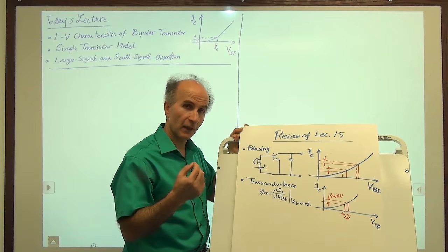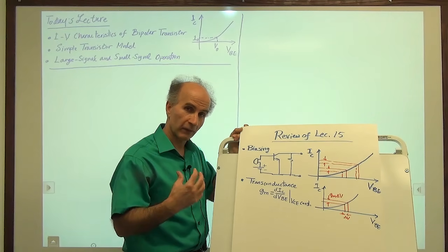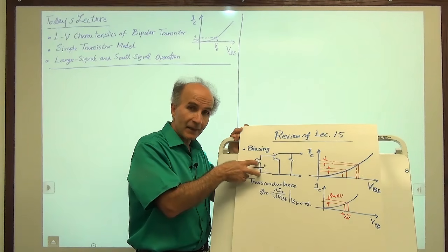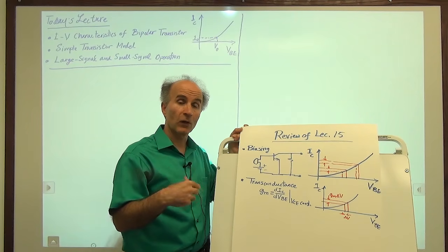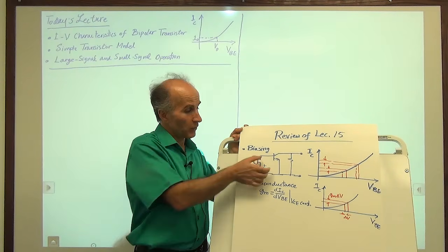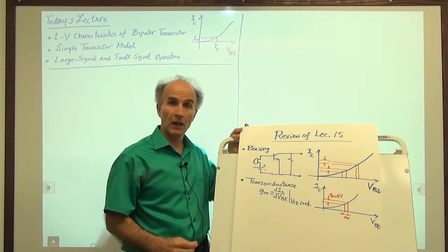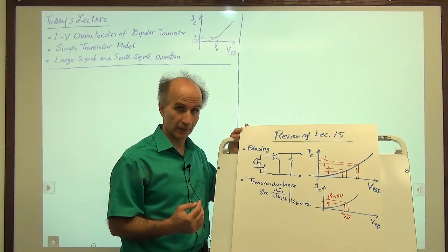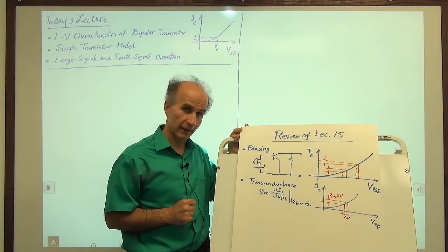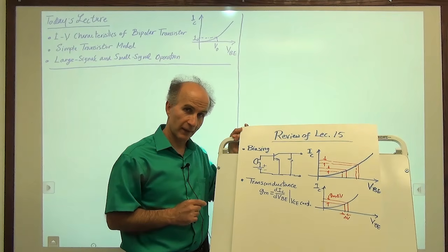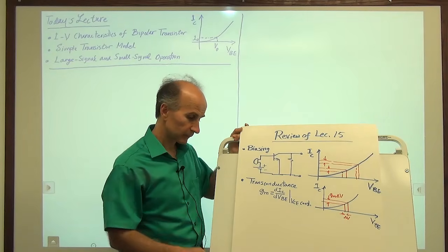The transconductance of a bipolar device tells us how much the device translates a voltage change to a current change, how strong or how sensitive it is. When we change the base emitter voltage by some small amount, how much change in the collector current we get shows the strength of the device, and that's why we call it transconductance. The unit of transconductance is 1/ohm or Siemens.